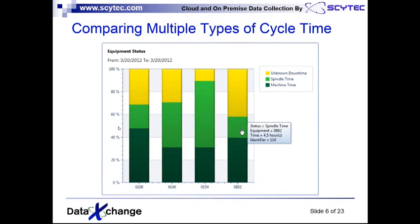This screenshot here is a sample of that, just showing when your machine is running and then when it's actually running with spindle motion. And you can see the difference there, the amount of time. So again, you can turn on or off any of those definitions of cycle time through the charting while you're collecting both definitions at all times.